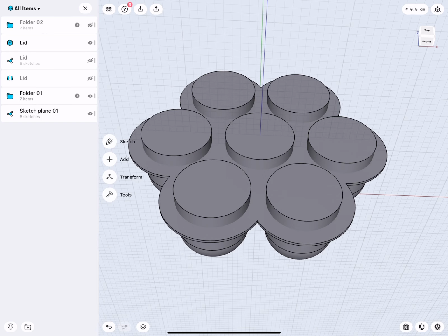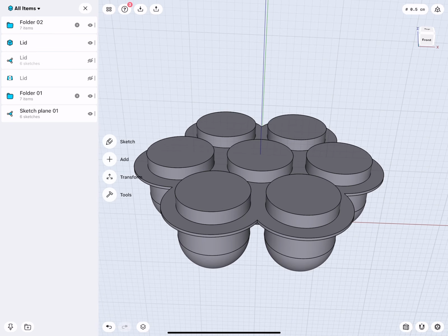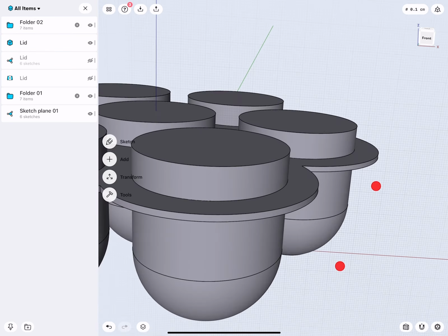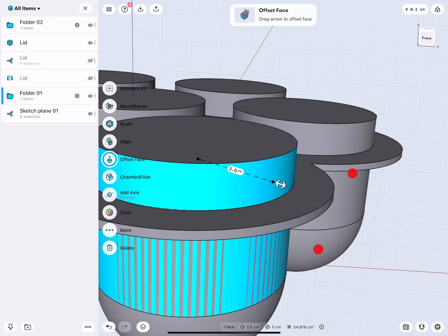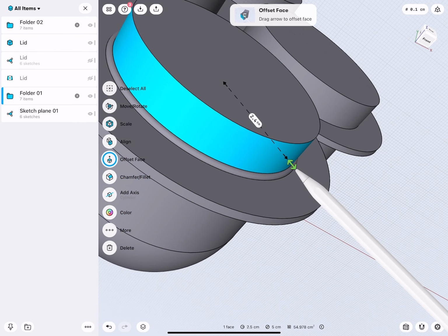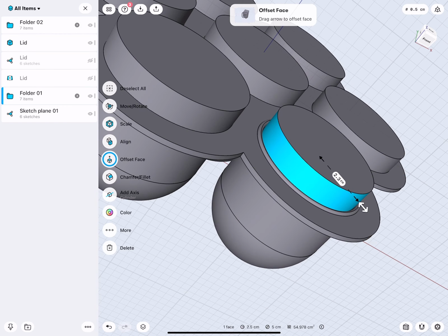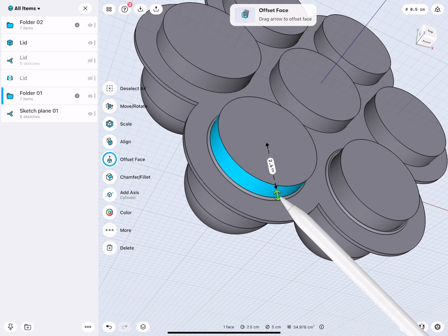And you see it sticks through. But they completely occupy the volume of the whole design. So we shelled our second copy by 2 millimeters, which means we then have to change this by 2 millimeters. So from a radius of 2.5, we have to change this to a radius of 2.3.